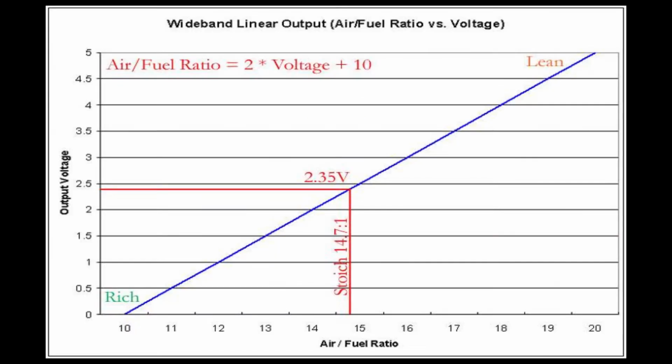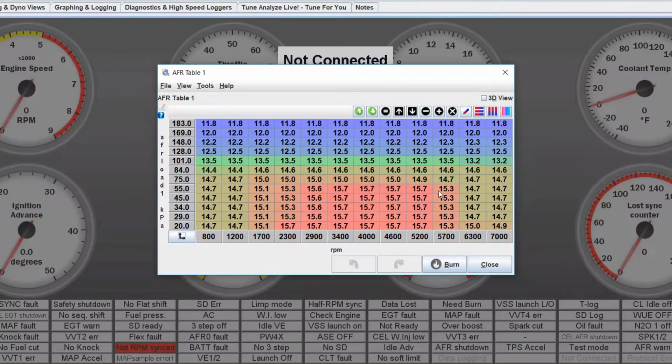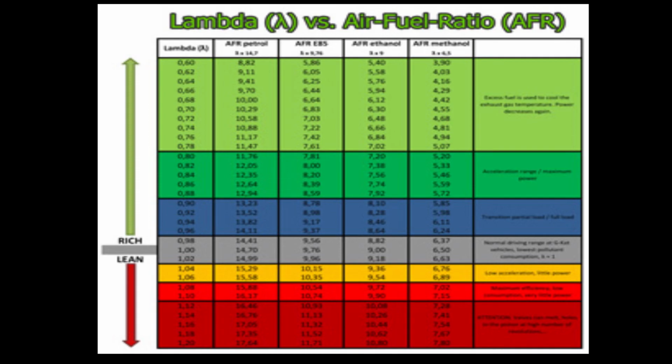Your gauge and controller then convert this to the typical gasoline AFR for display purposes. There's no reason to change anything about your gauge, your sensor, or even your AFR targets in your tune. If your brain thinks in gas AFRs, not Lambda values, then feel free to continue to do that. For the most part, AFR targets used for gasoline can be used without problem for E85.